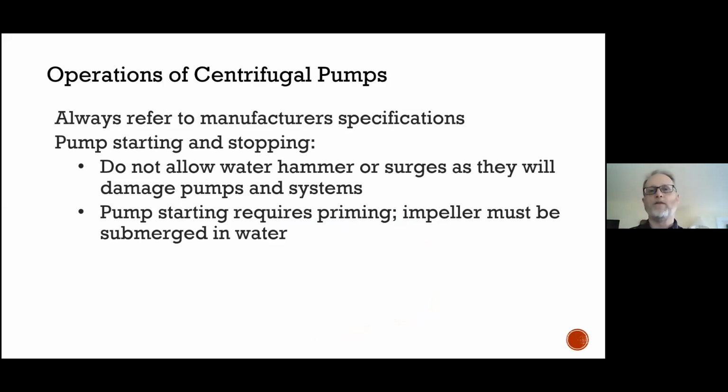So imagine we're moving water from one block to the next, but we have to lift it 20 meters. Well, if something happened and that 20 meters of head came back up against the pump, it could damage it. But by the same token, if that pump were to turn on and suddenly move that extra 20 meters of energy through the system, it could damage the discharge piping. So we try to minimize the water hammer.